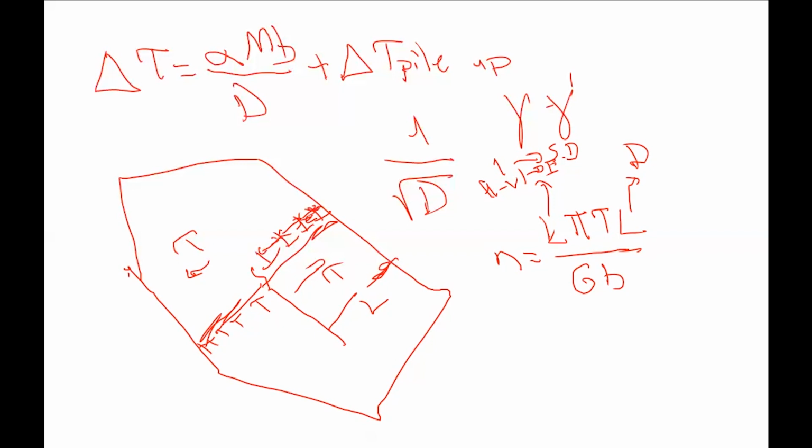And of course, once we have pileup, we will have some stress concentration. Consider a grain that consists of a single dislocation source like this S. This is the source in the center. Dislocations emitted from the source can go this way or this way within the individual grains.